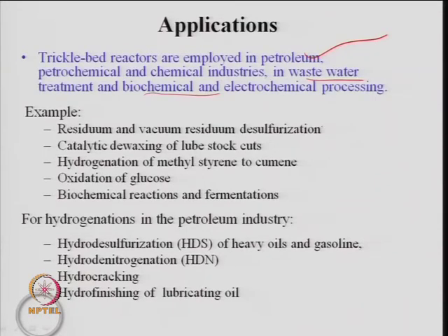I told you the trickle bed reactors are widely used for the hydrodesulfurization reaction. The residuum and vacuum residue contain a large amount of sulfur, which is mercaptan, benzothiophene, and cyclic sulfur compounds, basically disulfides.